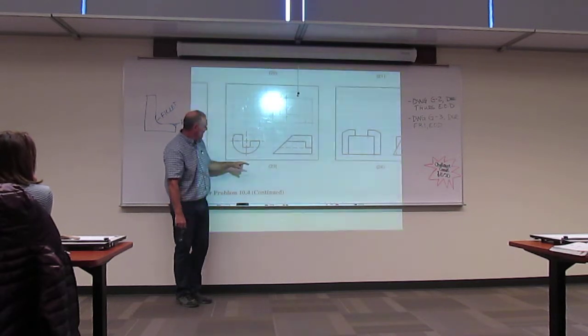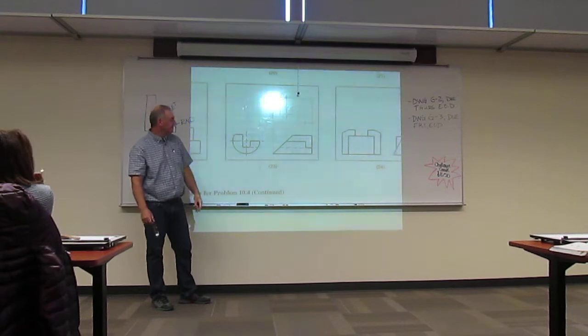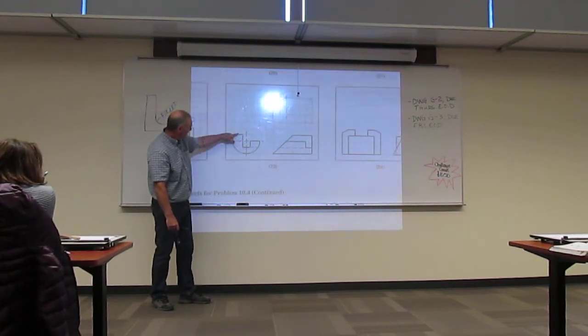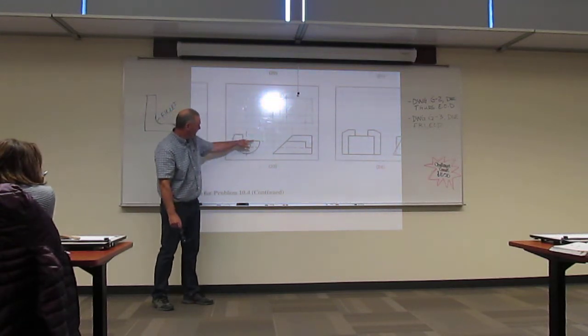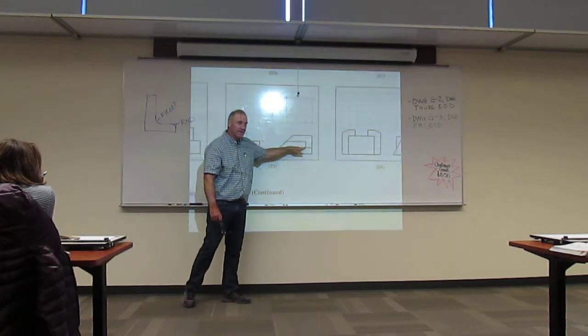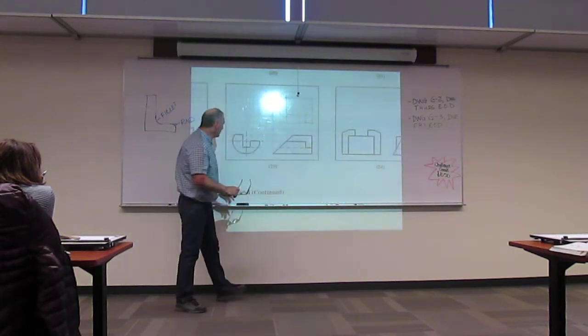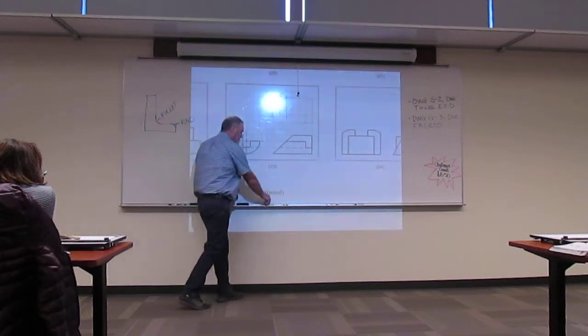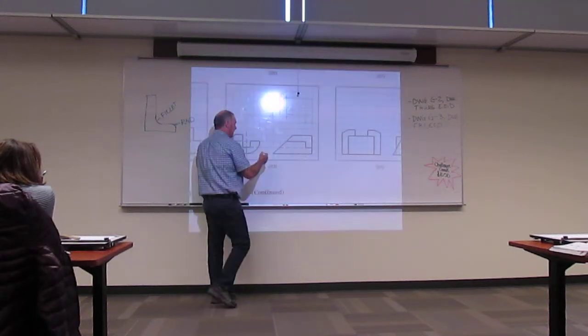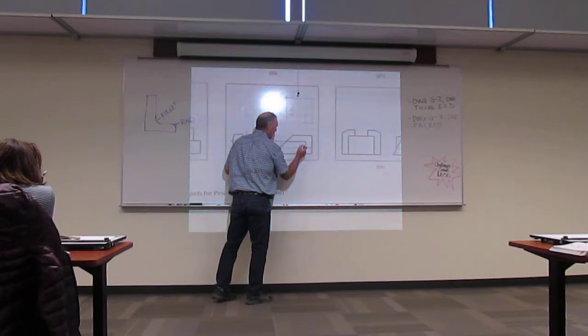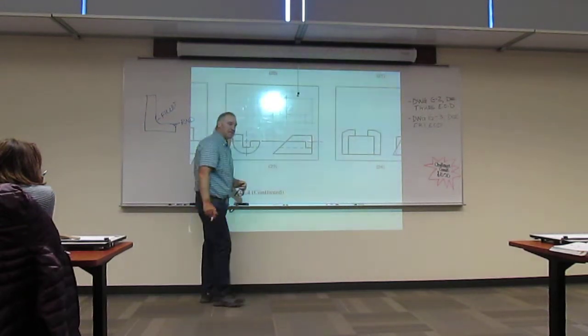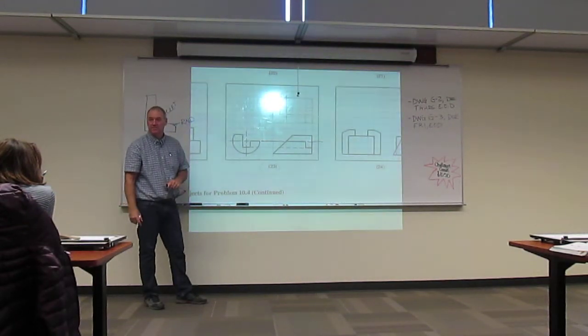Now, once I have that, then in essence, I've got 3 cuts on this guy I need to track. I've got this one, well, 4 actually. This one, this one, this one, and then I have another cut that occurs back here. Now, the thing you really want to pay attention to when you're looking at cylinders and where they're cut, you're going to base them off that center line. Okay? So there's the center line on both views.